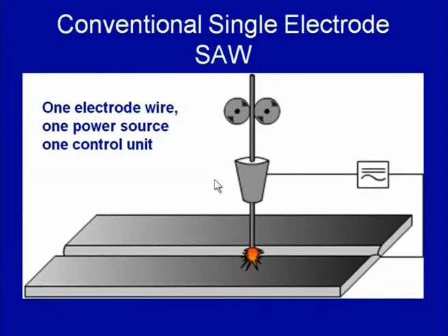So, the transfer of the molten metal from the electrode tip to the weld pool can occur in different ways in submerged arc welding, depending upon the welding current being used, the settings being used during the welding, the diameter of the electrode being used, and other characteristics.